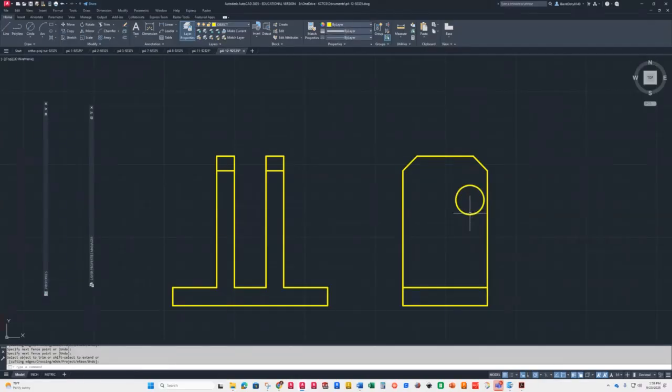Okay, well, I can draw my hole over here now. So I need to go to the hidden lines. I need to go to line and draw me a line from here over to here. Like so. And then we can do some trimming. And there are those 2 holes, because it said 2 times, 2x. So there's one there, one there.